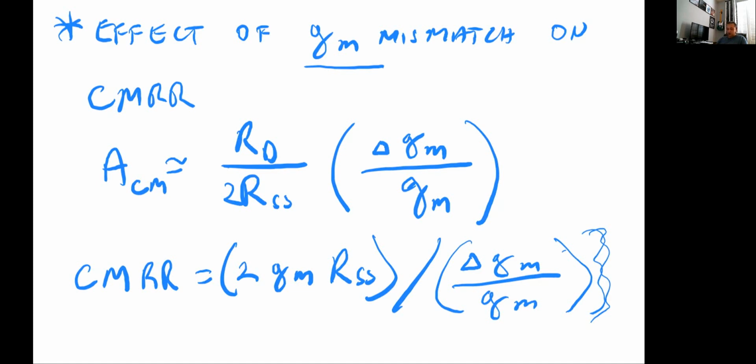And we're going to see that we have to do that because we cannot keep operating differentially. As you know, the op-amp eventually has an output that is single-ended. Most of them, we could do a fully differential amplifier. That's not what we're doing. That's a little bit more complex. So we're doing basically your plain op-amp with two differential inputs, one single-ended output.